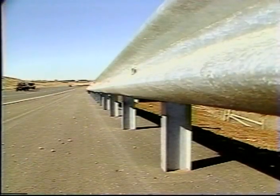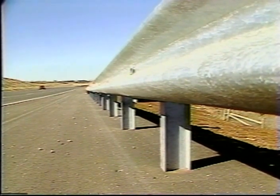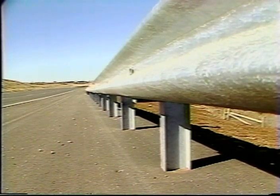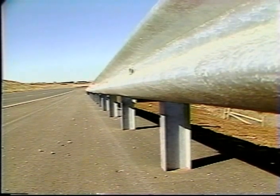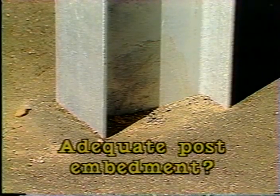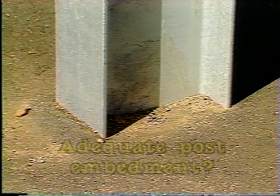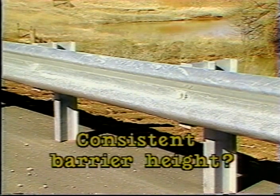The standard section makes up the longest part of the barrier and should be inspected as closely as the other sections since it is the part of the guardrail that absorbs most of the impacts. Here are some questions to ask when you check it out. Are the posts properly embedded? Is there enough soil behind the posts to prevent them from being pushed out on impact? Is the height of the barrier correct? Is it consistent through the system? A range from 24 to 30 inches to the top of the rail is a common requirement.